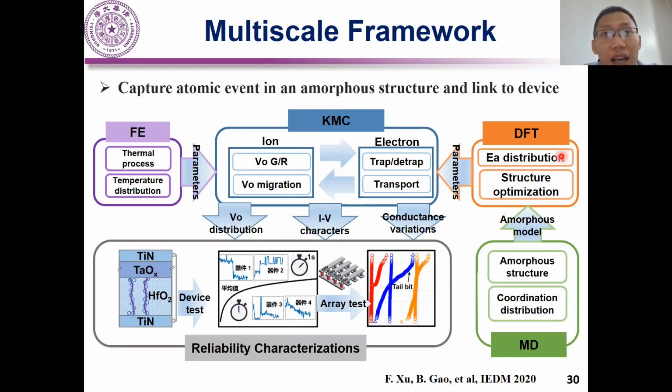We also use DFT to calculate the distribution of activation energy on the different lattice points and get the distribution matrix. And then we input these calculated parameters to the KMC simulator and finally calculate the device electrical behavior and reliability characteristics.